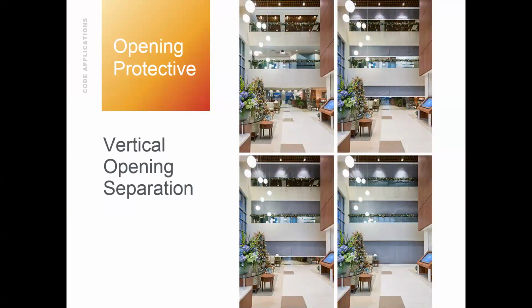Design team and the AHJ said, look, if a fire were to break out within this atrium, all these corridors would be sucking wind into there, just channeling more and more fuel to that fire. To be able to close off each opening for no air transfer to come into that atrium, that's what they went with here. So it was a smoke evacuation system coupled with the 20-minute rated fabric product at 3 of the openings, not just 1.